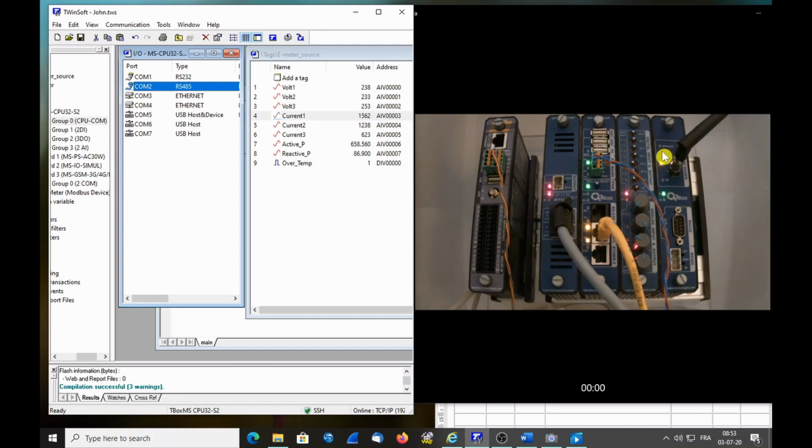The first one on the top is the network LED. It indicates the GSM is registered to the network. The online LED indicates it has received an IP address. It's connected. And then we have the transmit and receive. When it communicates, we see here sometimes a little bit of flashing because the GSM communicates to the network. This ends this video about Modbus transaction to a remote device.